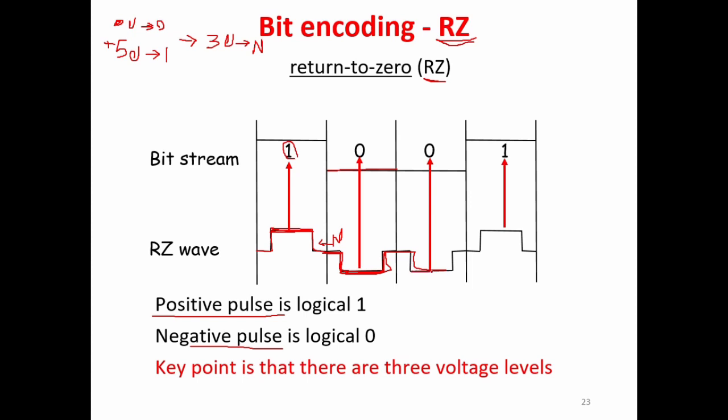And here, likewise, the signal is decreasing, so we index 0, and here the signal is increasing, so we index 1. Now, instead of this very oscillating signal, we are representing this type of signal using RZ as this. So 1, 0, 0, 1 for the different time intervals that we are working with.